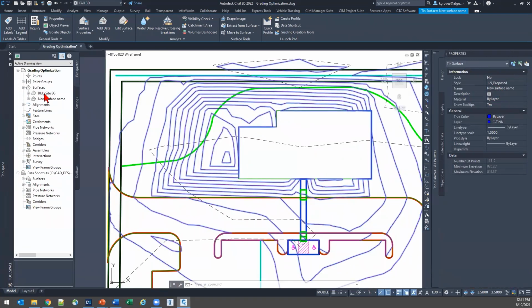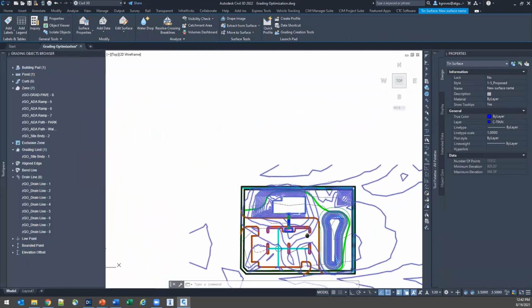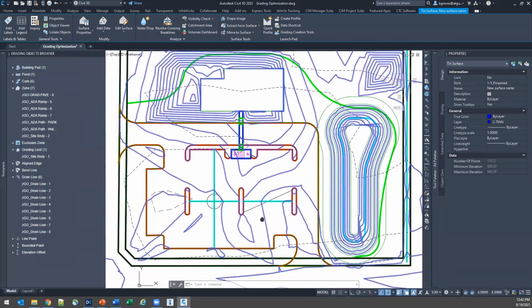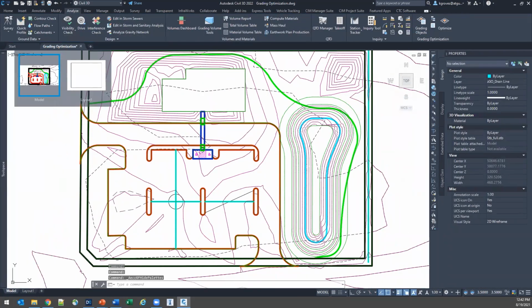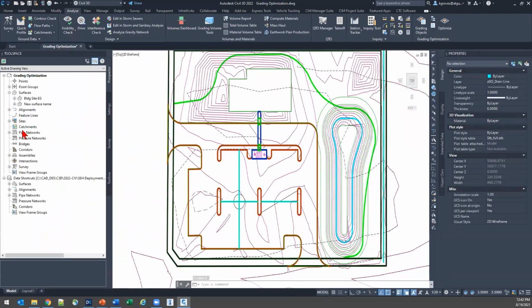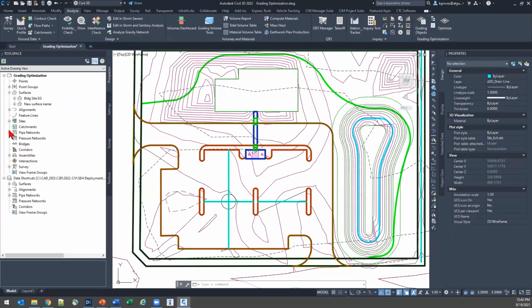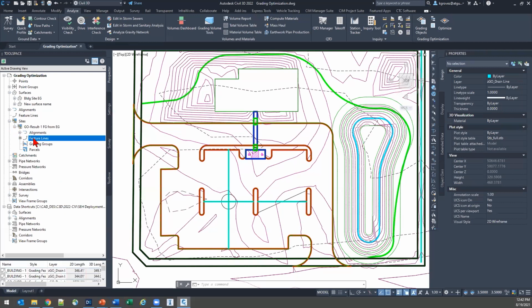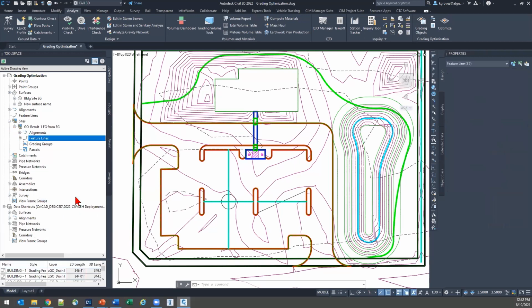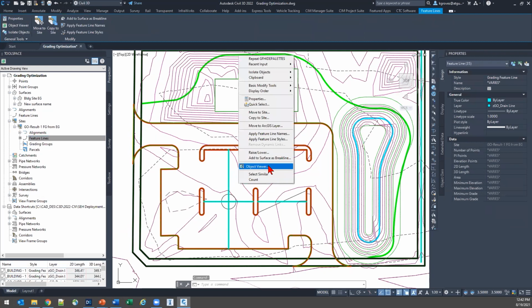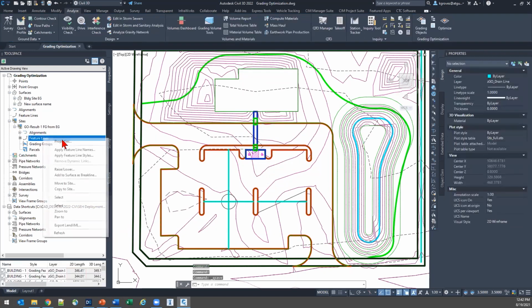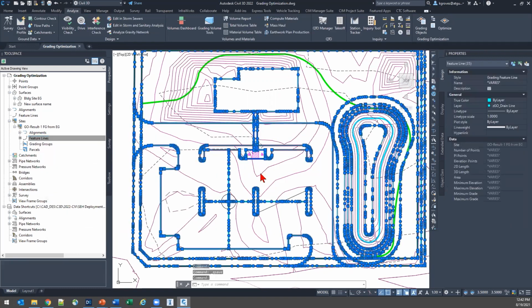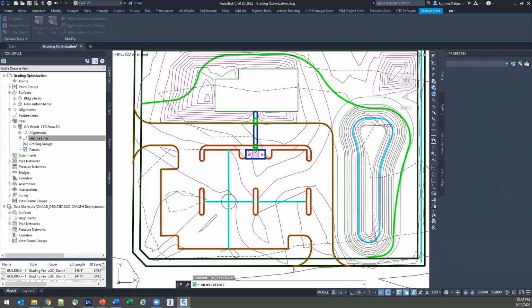But I could have. So there's my EG, there's my building surface, and now I can create a Civil 3D volume surface. I can run the elevation banding on that. Again, let me get my tool space out so we can work with this a little bit more. On those sites for my feature lines, select all. Let me save this. Always save before going into Object Viewer. I just want to check out these feature lines to see how they look.